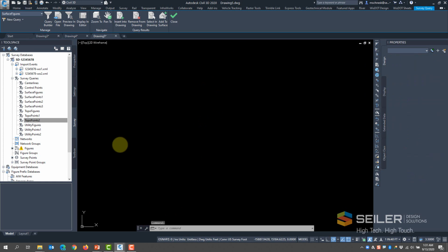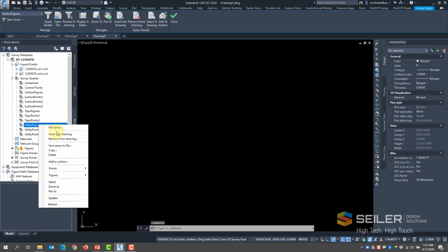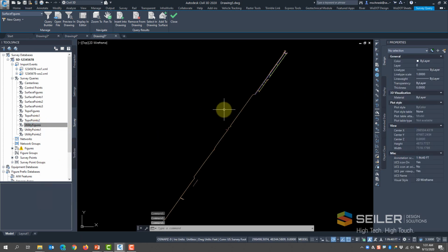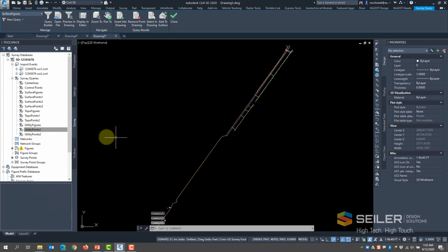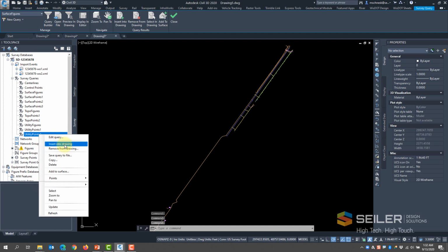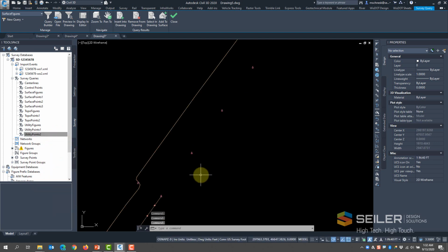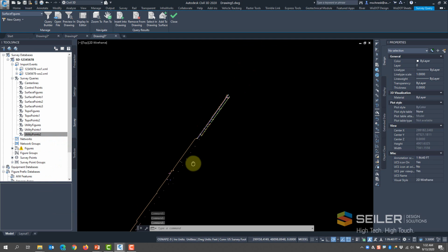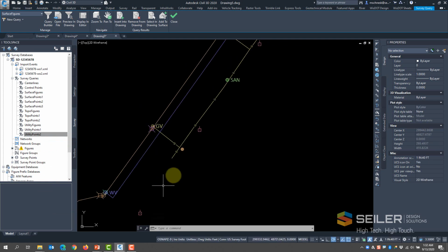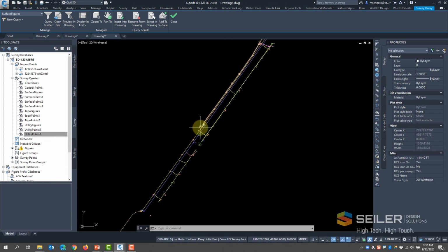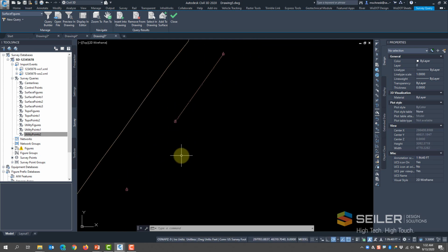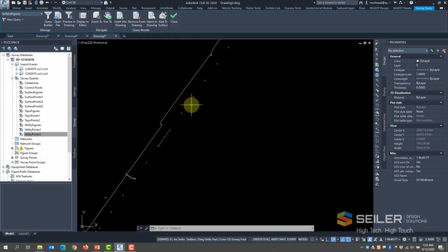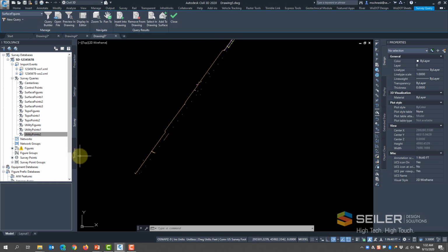And the last drawing is going to be my utility drawing. And here I can bring my utility points or lines in, and utility points, and more utility points. There we go. So here's some power poles and some overhead lines. So these are all things that become utility points, utility figures. And now the query is not 100%. Notice I'm missing some overhead. I guess I have to go back through and see why these didn't come in as part of my query.